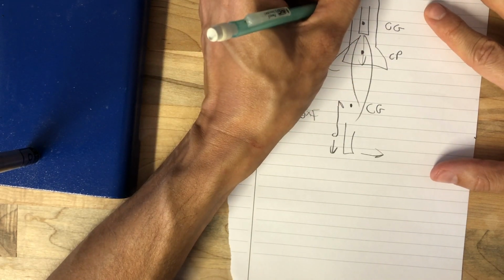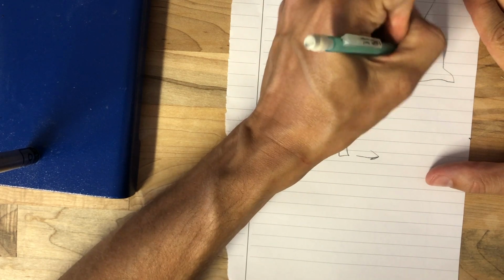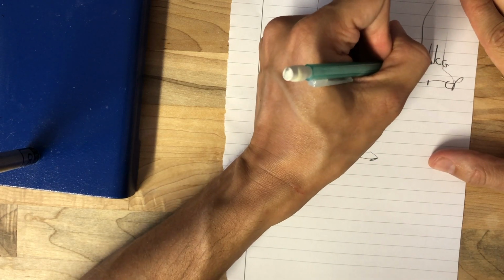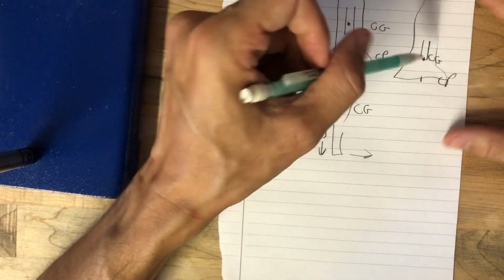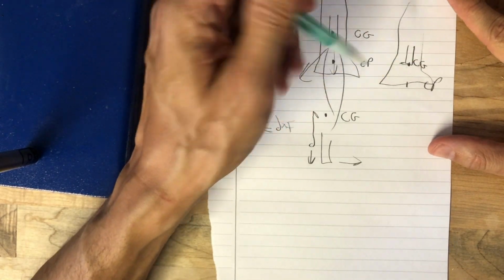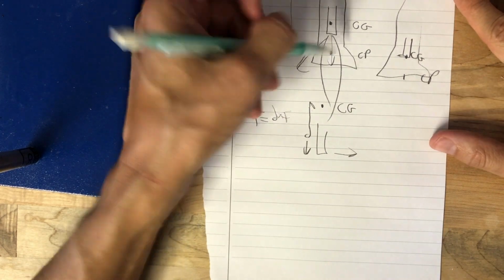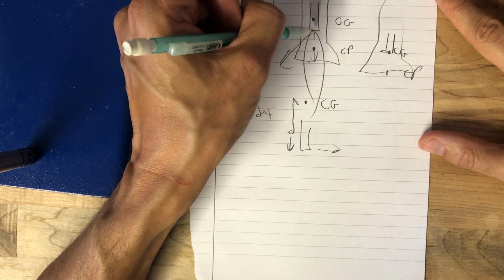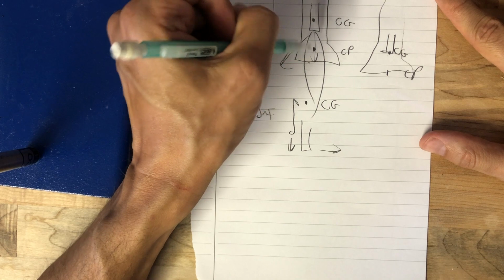So if we minimize this distance, i.e. we move the motor such that it's pushing out right at the CG, so I have my rocket, say the motor's right in the middle and the CG is right here and the CP is right here, then any non-downward force that goes out sideways would actually not change the direction of the rocket. So that's desirable. So when I did my rocket, I pushed the motor up higher than you would expect. Typically you'd see the motor way at the end. I didn't want to do that because then I'm getting rid of the torque from non-ideal exhaust direction.